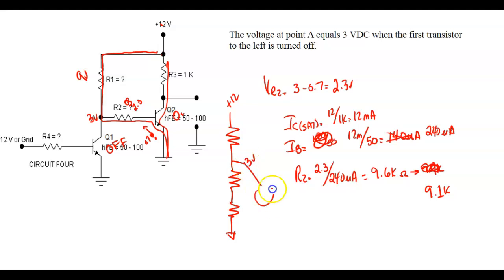All your measurements are from there. So I measured 3 volts right there, so the sums of these two down here, since that's the ones I measured, has got to equal 3 volts. But I don't need to know that. I need to know I got 3 volts right there, I got 12 volts right there, I got 3 volts right here. So what is that resistor right here got to drop? Listen, 9 volts.